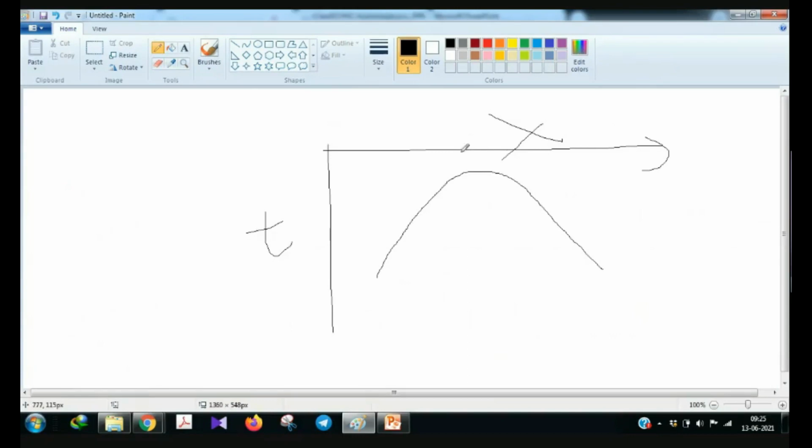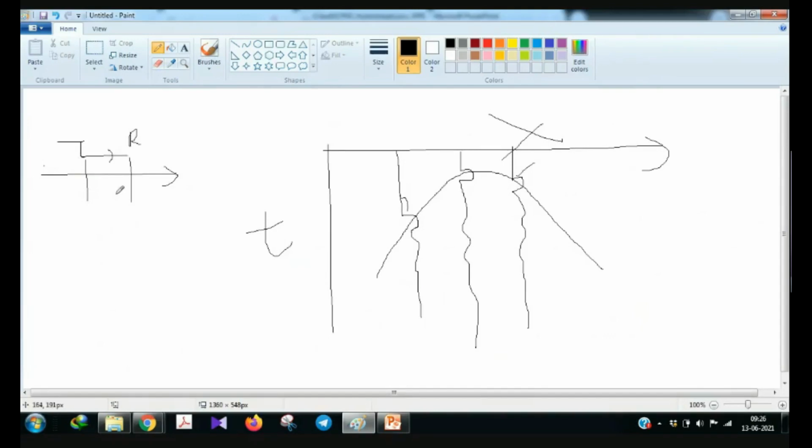And the traces will be, for obvious reasons, if you are increasing the transmitter and receiver distance, the first arrival will be late. Suppose this is the initial transmitter-receiver distance. The direct wave will be reaching the receiver. Direct wave means the signal coming directly from the transmitter to the receiver, not via the subsurface. Suppose it will take 1 nanosecond.